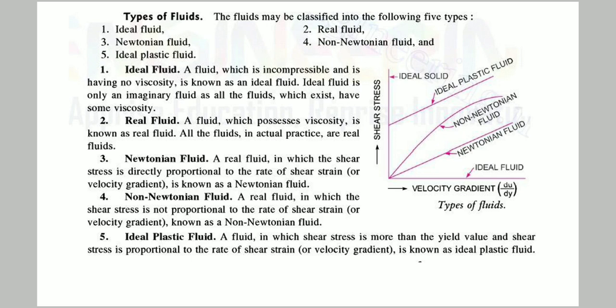Generally all fluids in actual practice are real fluids. The fluid which obeys Newton's law of viscosity is a Newtonian fluid, and that which doesn't obey it is a non-Newtonian fluid. And an ideal plastic fluid is one where shear stress is more than the yield value, and shear stress is proportional to the rate of shear strain or velocity gradient.